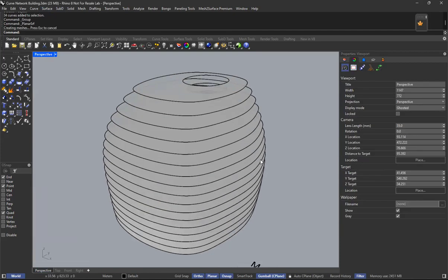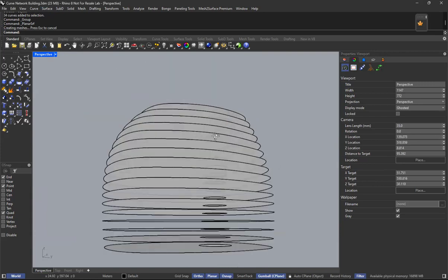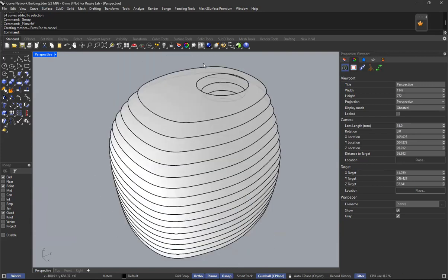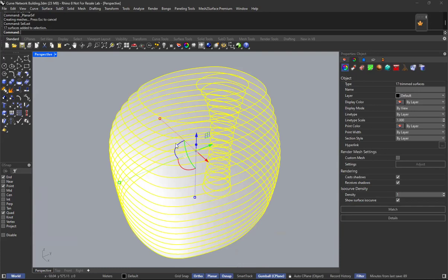Okay, I'm going to show you that the surfaces are all done. Next, I'm going to select last. Select last will select the surface planar, and I'll Control G on the surface planar. So I'll group them, and then solid,